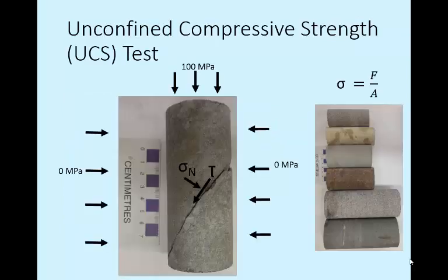In rock mechanics, we routinely test how much stress can be applied to a rock before it fails. We are really just adding mass as gravity is constant, and the area doesn't change during the test. We carefully prepare samples, usually rock core from diamond drilling, so the ends are parallel and flat, as this ensures full and complete contact between the load platens and the sample.